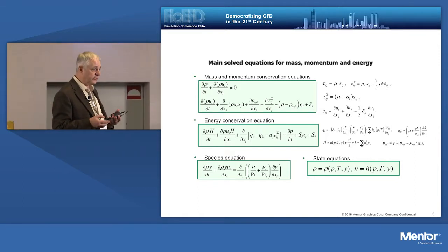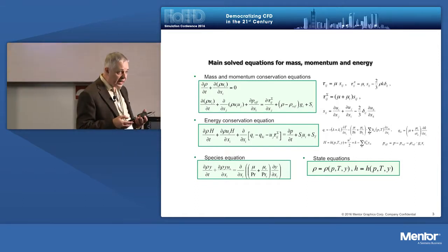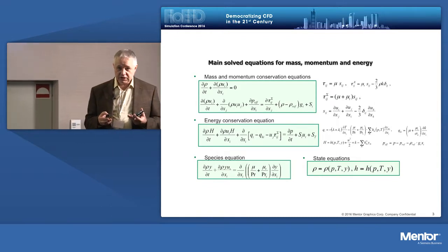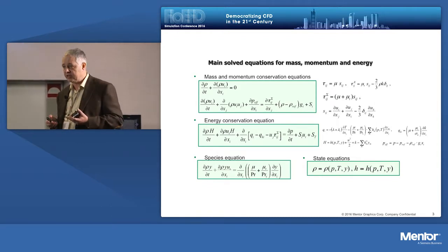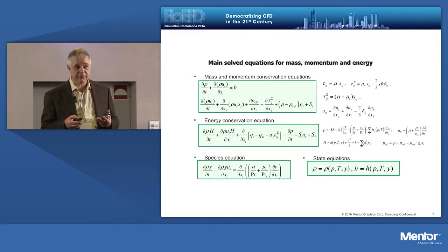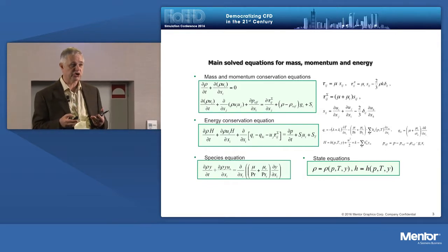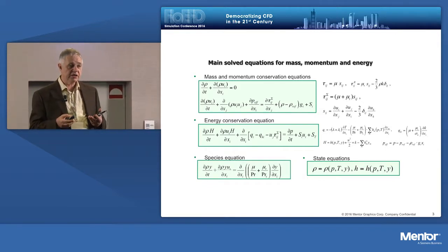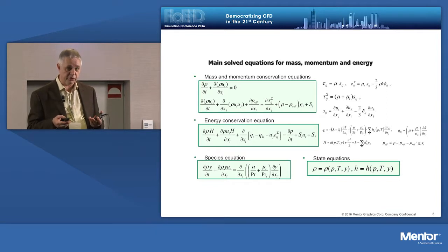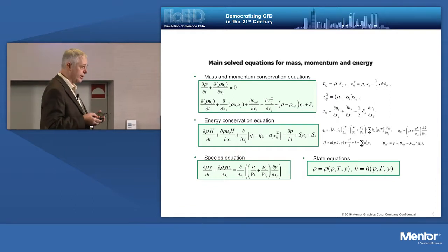Where is the difference and what is the issue? Why can traditional CFD not be fully CAD integrated? Why do we have issues with mesh generation? And why is it not so easy to make it robust, and why do we need to spend a lot of time selecting the correct turbulence models? The key element is the boundary layer.